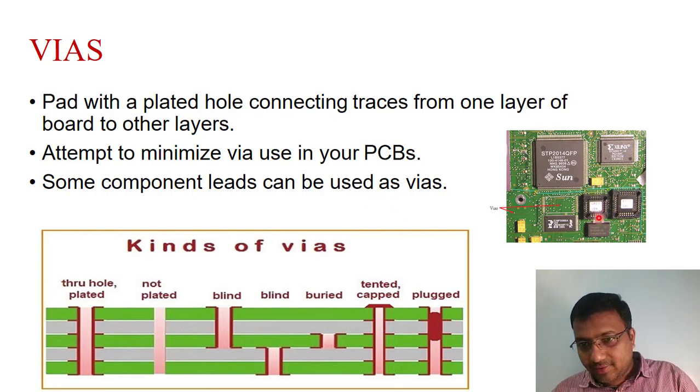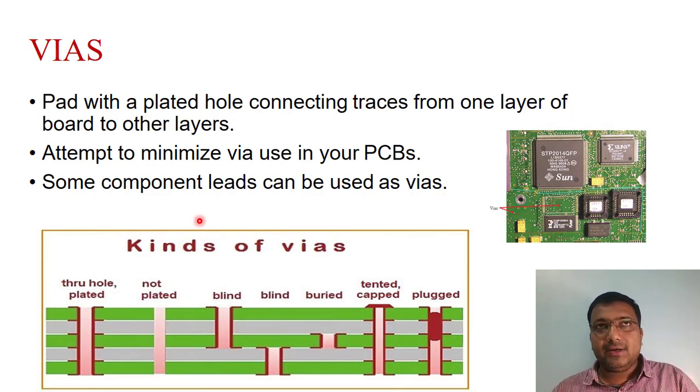So here there are different wires in the PCB. So many wires are there. This is a big complex PCB, so we have to see the wires here. There are different types of wires available. So, through hole plated wire. Through hole plated means from the top till the bottom layer. Not plated wire means there is no connection, only a drill point is there. Plated means copper is available here.